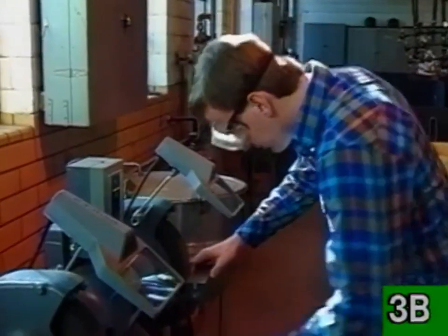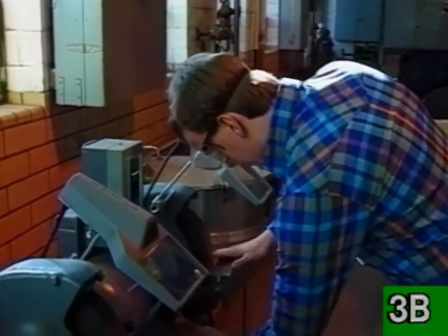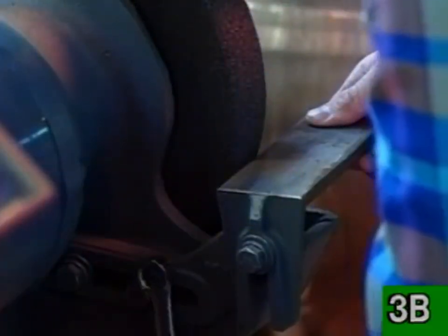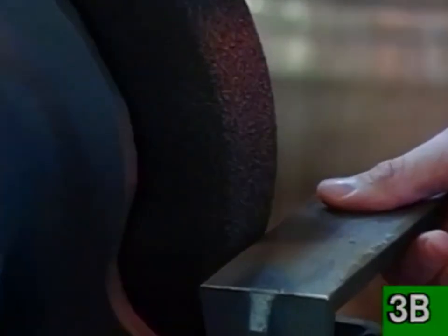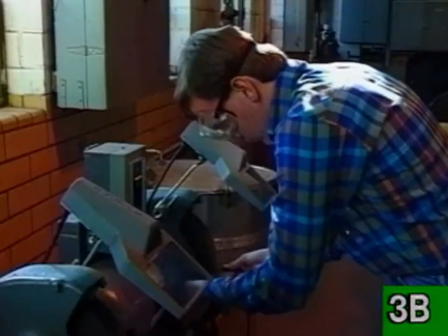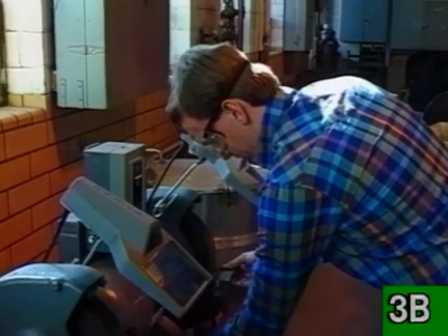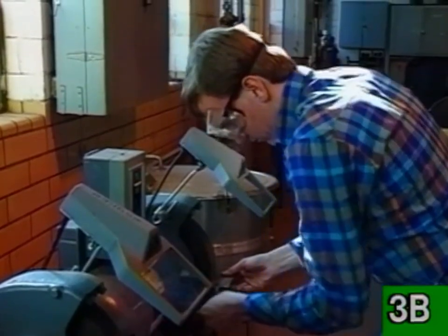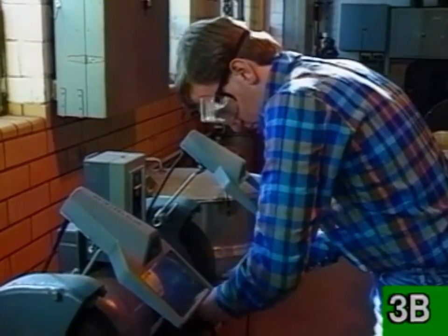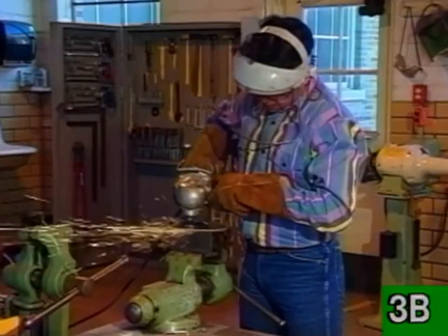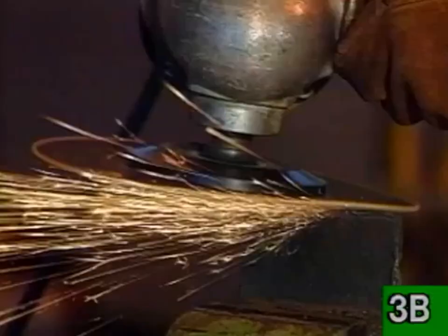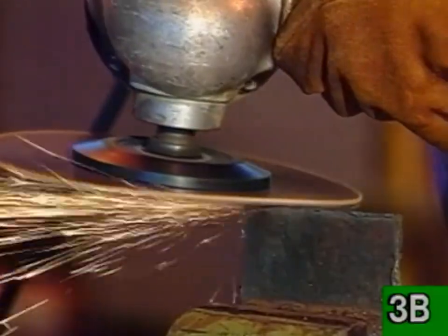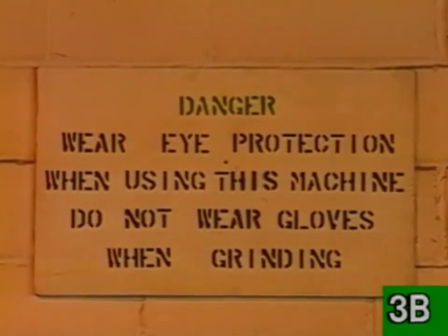The grinder is another tool that must be properly guarded and adjusted. The tool rest must be no more than 1/8 of an inch from the grinding wheel. If the tool rest is further from the wheel, there is a danger of having fingers or materials lodged between the rest and the grinding wheel. Remember to wear eye protection when operating mechanical equipment, and do not forget the face shield if flying fragments are a possibility. Do not wear gloves when operating moving machinery.